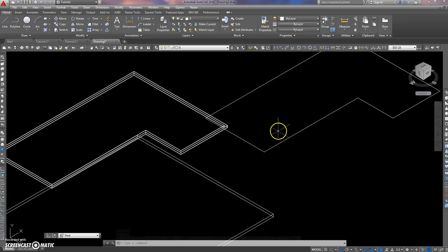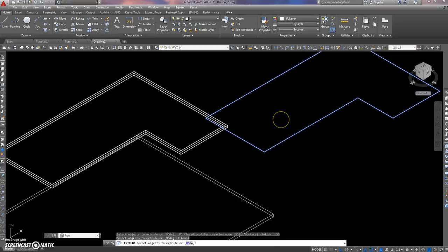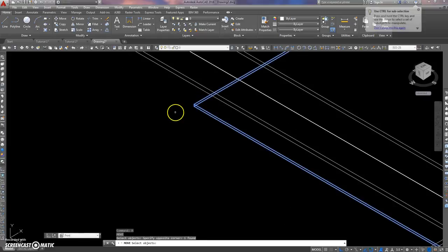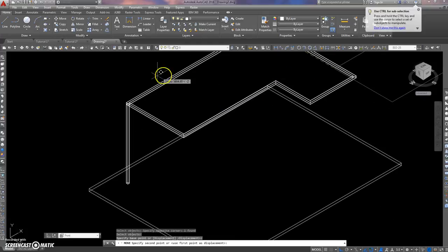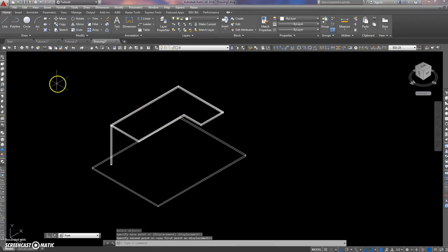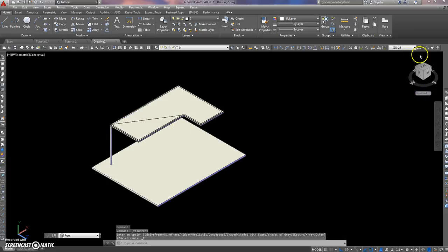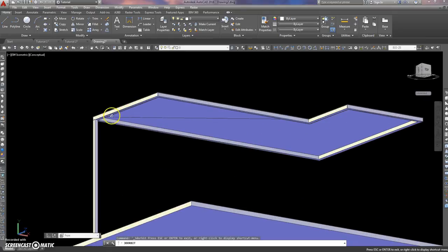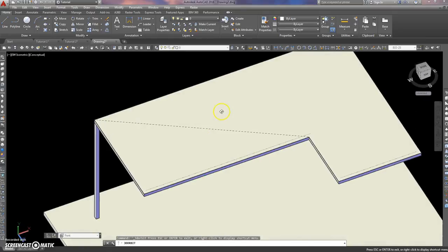Okay. And in the meantime we'll put this piece that we had hiding over here, we'll extrude him. See the extrude button over here? And we'll make him 5 mil high. He's now a piece of 5 mil steel. So if you move this guy here, and we just pop him on top of there like so, he's now a piece of steel on top of there. And if we do a coloured inversion, you can see that. We can do all this sort of stuff, using that one there, but this one here will allow us to look underneath. We can sort of look underneath and see that that's what it looks like underneath.